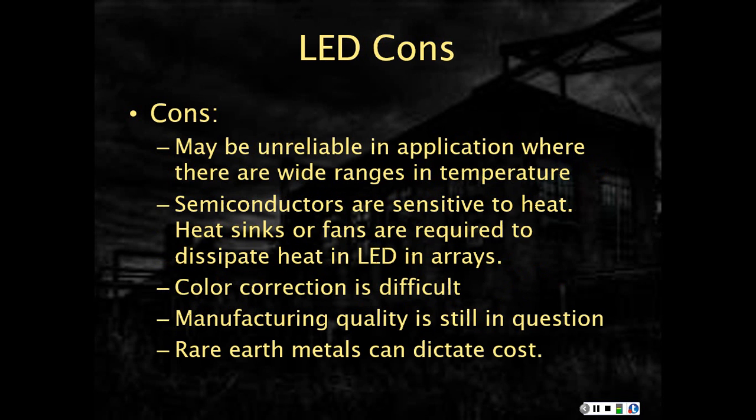On the con side, they may be unreliable in applications where there are wide ranges in temperature. They are an electronic device. They like stability. So if you have rapidly changing or wide-ranging temperatures, they don't deal as well. They are semiconductors, so they're sensitive to heat. Now, when you put a number of LEDs together to get more light out, this pattern of LEDs is called an array.